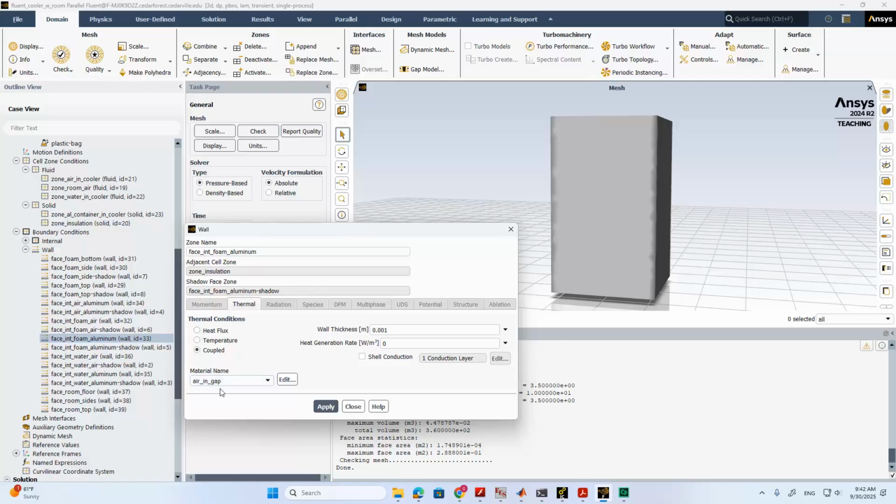There must be some air, here and there in those bumps or valleys along the surface. So I put one layer of air, okay, at such a surface, and I assume its thickness again is 1 millimeter, and in the future we will want to change the thickness, okay, to fine-tune our results until results match our experimental data well.